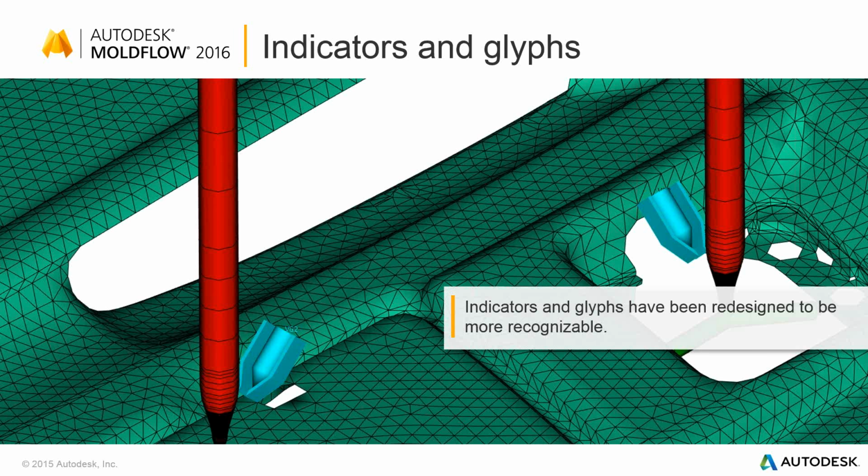Correct. So if you want to check out a license, you let's say install the software on your laptop. You do the borrowing explicitly from the laptop at that point. So you go into the Help About from on your laptop and check out the license from there. You don't actually have to interact directly with the license server itself.